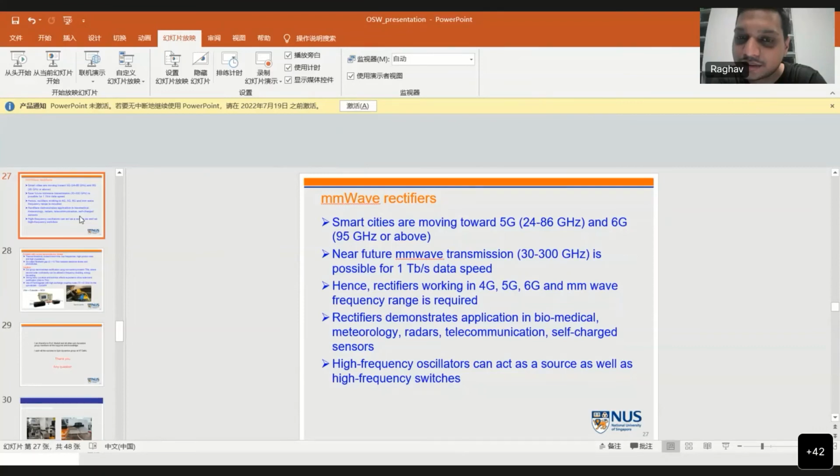So when you had this canted magnetization, these were orthogonal MTJs, right? Orthogonal means completely in plane? Neither completely in plane nor completely out of plane. Yeah, of course they were canted, at a certain angle. I'm just wondering, because in orthogonal MTJs we usually do not observe any sharp magnetoresistance change. They usually have a very varying magnetoresistance, right? Does it have any influence on the power, or maybe not?